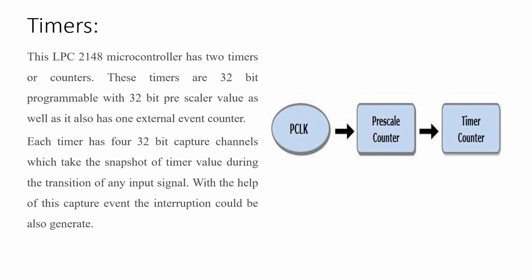Timing signals can be generated once the value in the match register and the timer control are equal. So it can reset the timer or stop the timer or generate some interrupt signals. In that timer PPT video, you can see the operation of the timer block diagrams, and a small program is there for understanding how it operates.